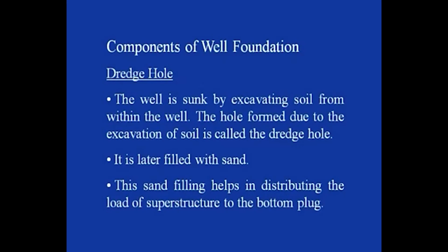Once the well has reached the required depth, this dredge hole, created because of the excavation of the soil within the well, is filled with sand. This sand filling helps in distributing the load of the superstructure to the bottom plug. How?